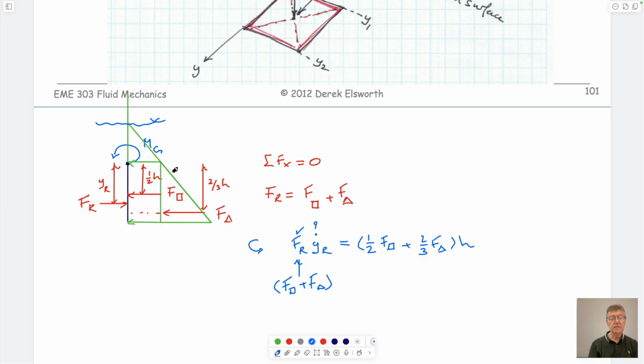If this was Z, then the pressure at any point would be equal to the unit weight of water times Z. At this point, Z is 0. Forget the fact that we've ignored our sign convention. Then as we go further down, it would be equal to a larger number.